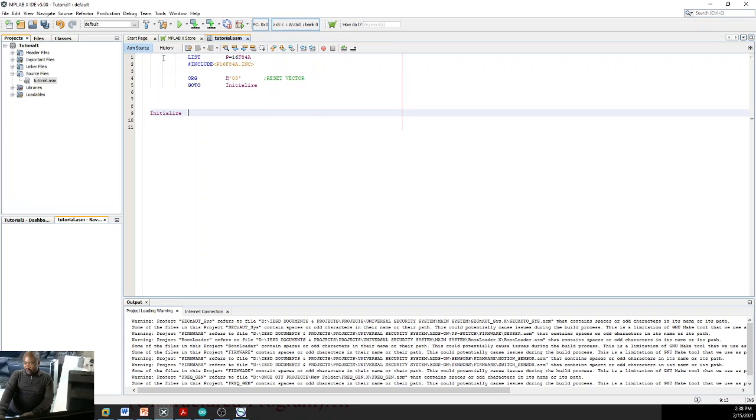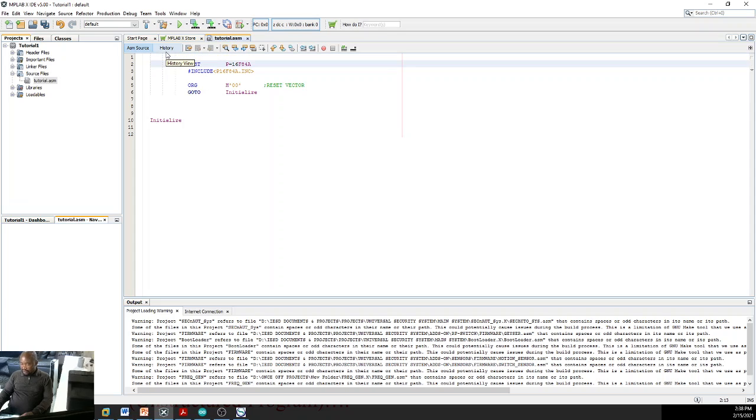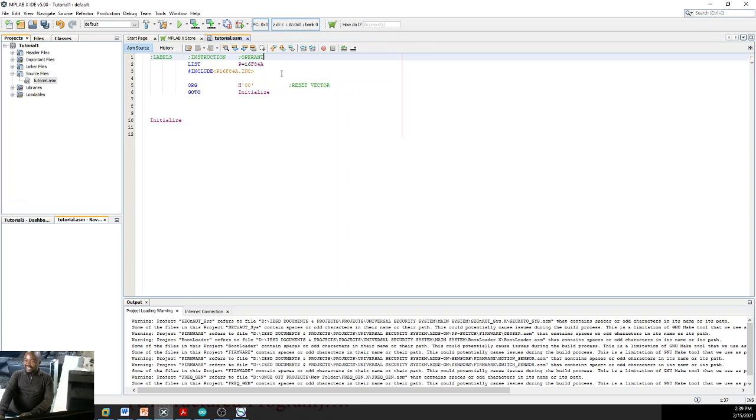So when we write your PIC program, let me also do this. I'll add these things as we write the program. So here at the margin, I leave spaces at the margin because the margin is for labels, like initialize and stuff. And now the next part of your assembly program structure will be the instruction, the assembly instruction, and then the next part, they call it the operand, where the instruction is being imposed, or whatever the case may be, right?